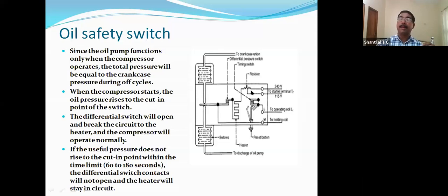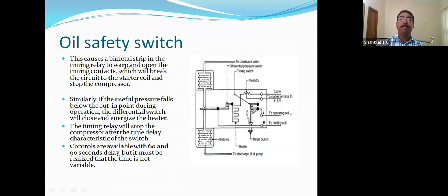The supply goes to the heater and it keeps heating. This causes the bimetal strip in the timing relay to warp and open the timing contact, which breaks the circuit to the starter coil and stops the motor. In this way, the motor is stopped.